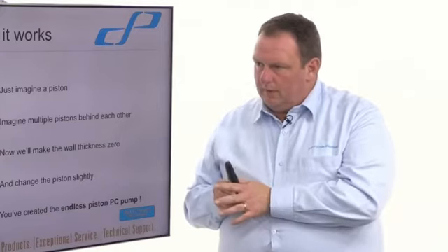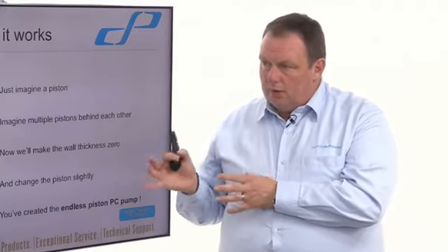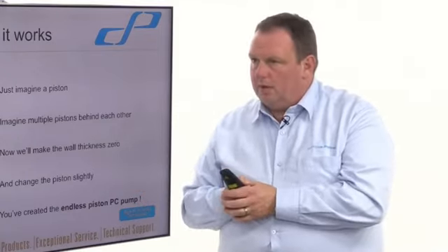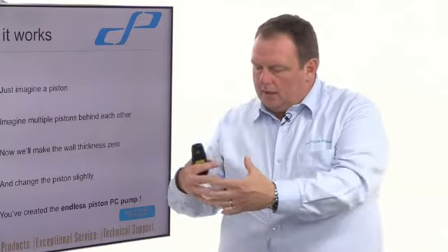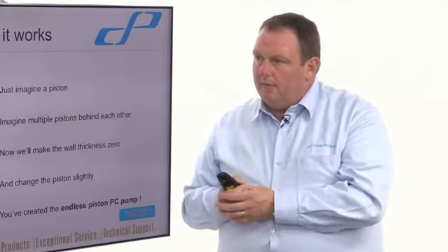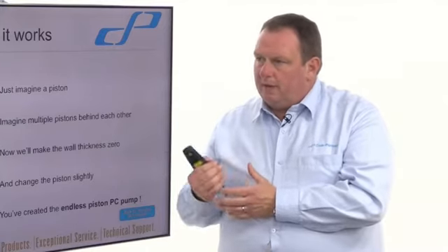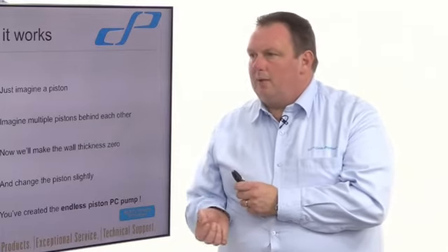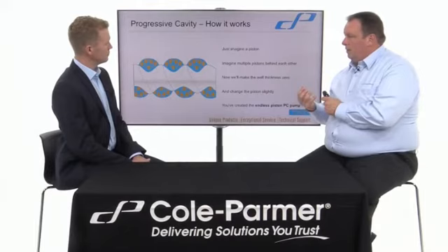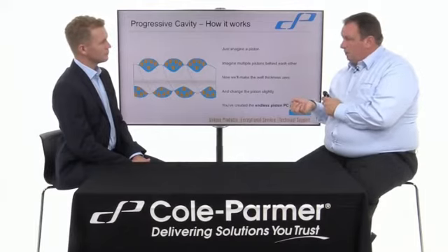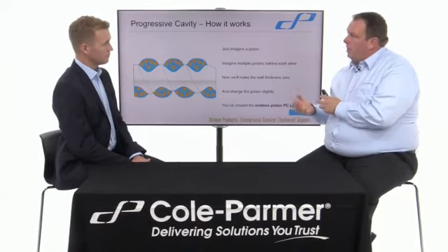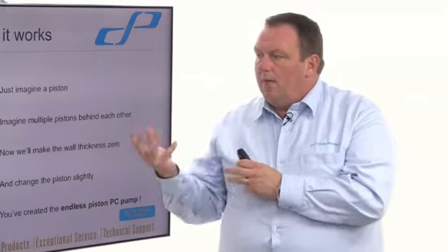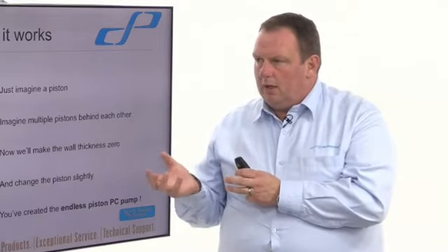That's talking about foodstuffs. Because they're also low shear, they win on the foodstuffs, and they can win on other valuable products. Within the food industry, being low shear makes them very, very effective. They're very effective as well for a lot of the clay slurries and china clays we use, so a lot of the ceramic ware is also pumped with this. Now, the china clays and things are even more aggressive and abrasive, so they do what they call nitriding on the rotors to make sure they don't wear out. They do many, many different things to ensure they last.